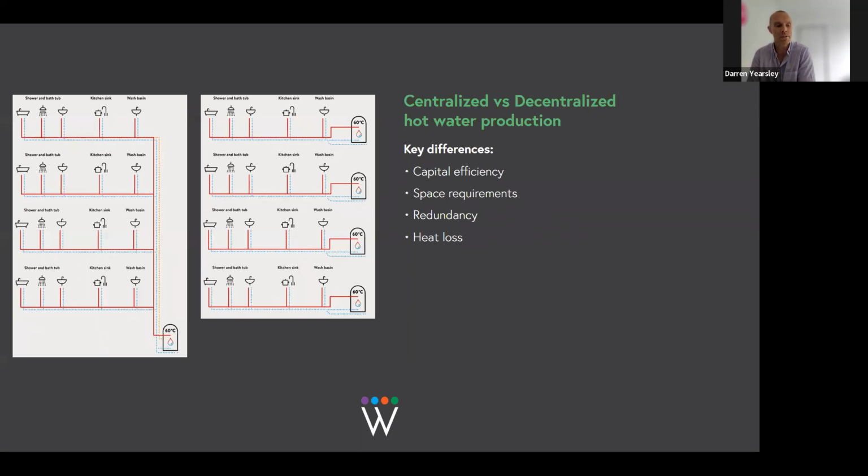So the water cylinders themselves aren't particularly well insulated, and they become more well insulated as they get bigger, which is a little bit counterintuitive. But in terms of heat loss per litre of water stored, you lose less energy as the size of the cylinders go up. So that's just something to keep in mind when we're thinking about the overall efficiency of the system and some of the reasons why you wouldn't go decentralized versus centralized.